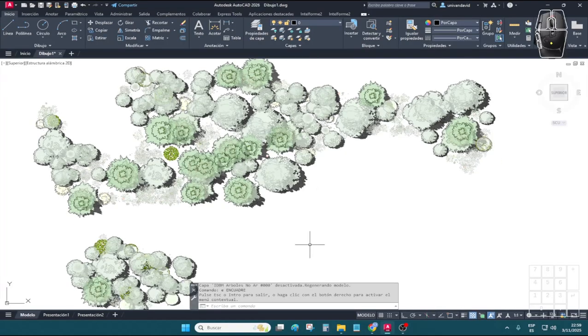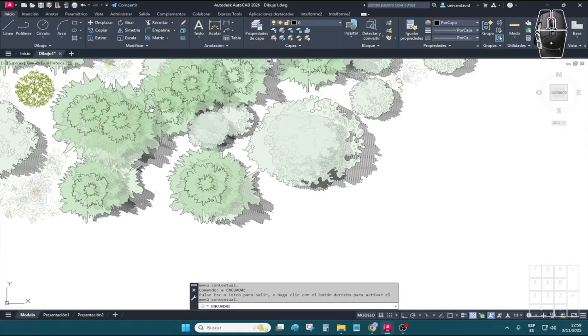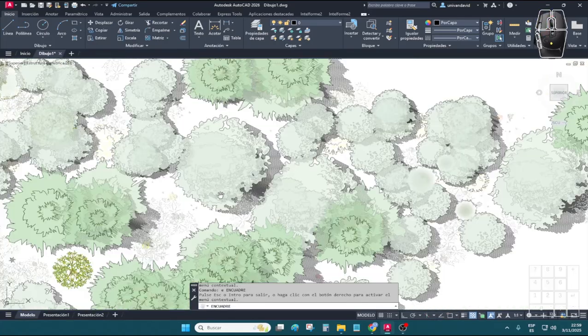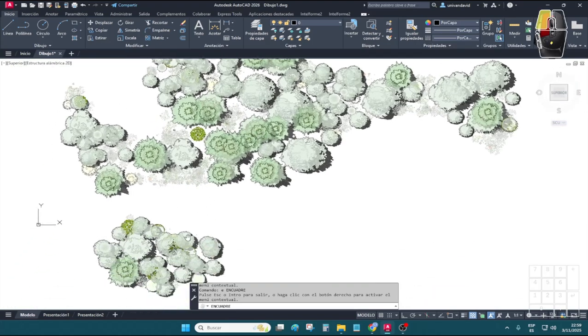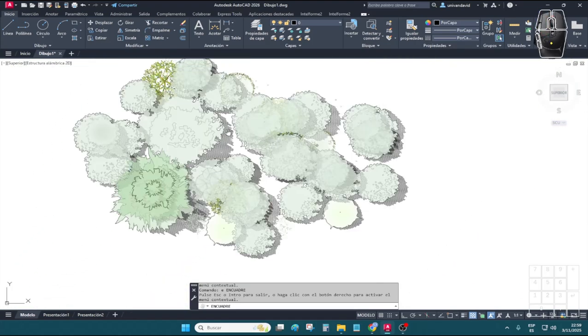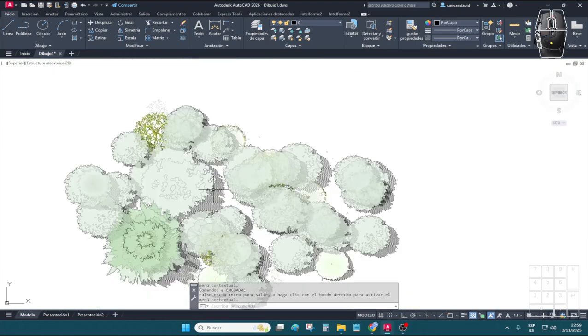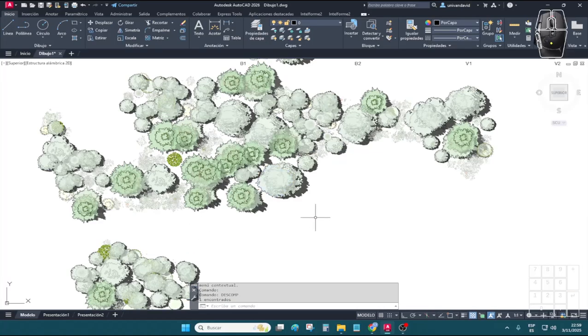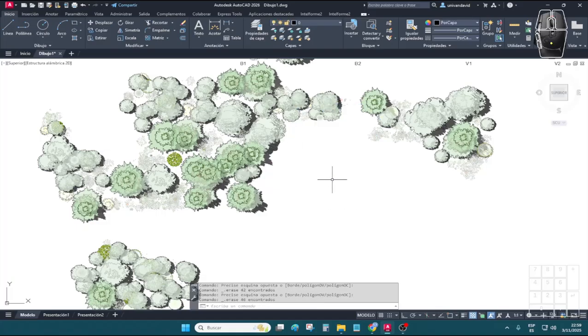We must keep in mind that the drawing created is simple AutoCAD geometry: polylines, lines, fills, blocks, etc., and everything is created as a single general block. If we want to edit or delete any part of this block, we simply explode it and edit or delete what we see fit. So, you see, it's something simple and practical.